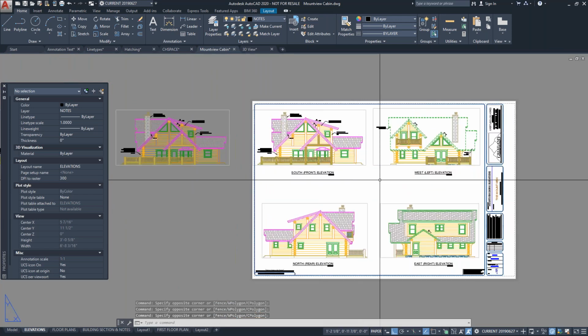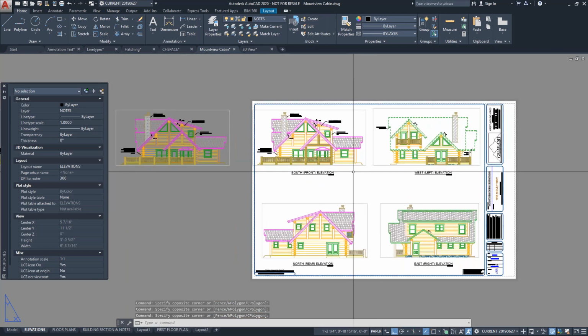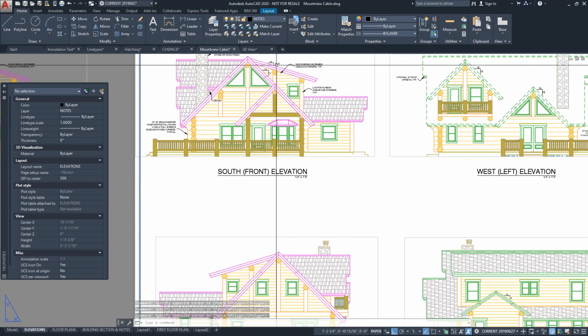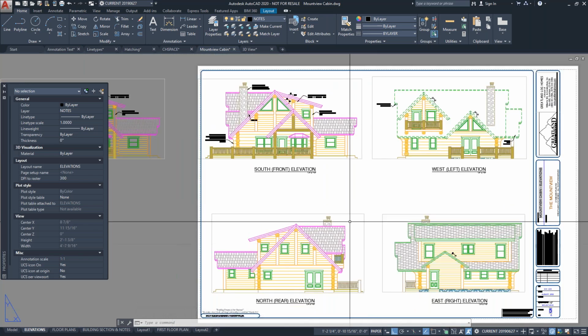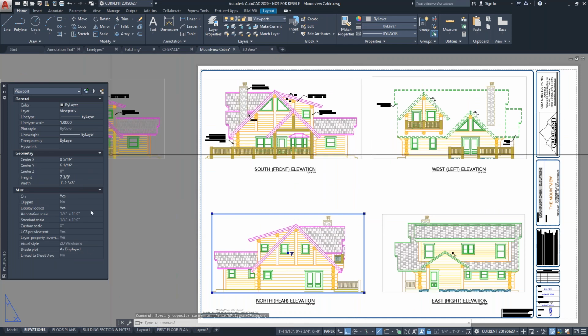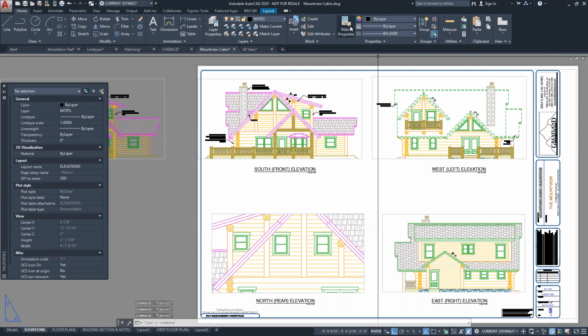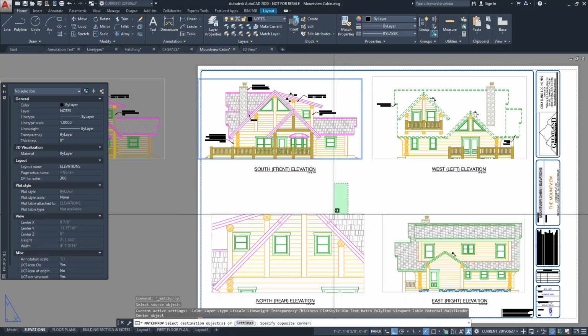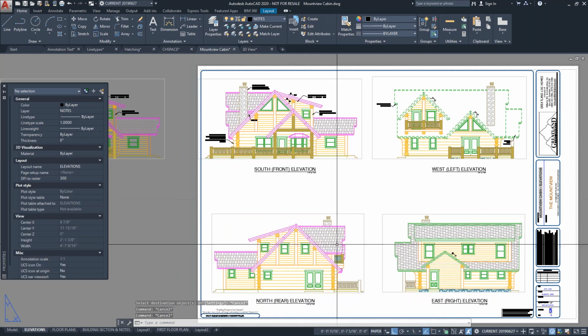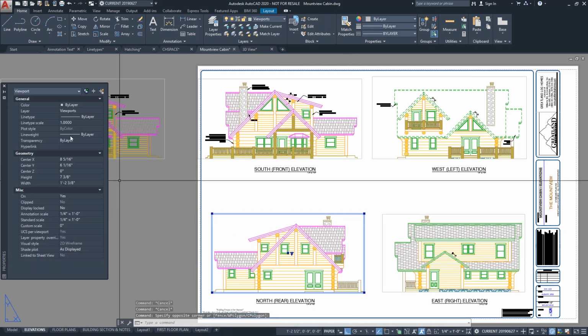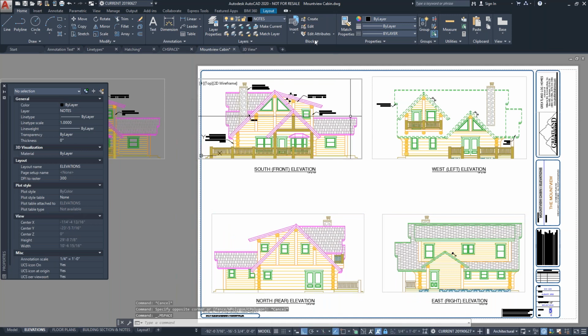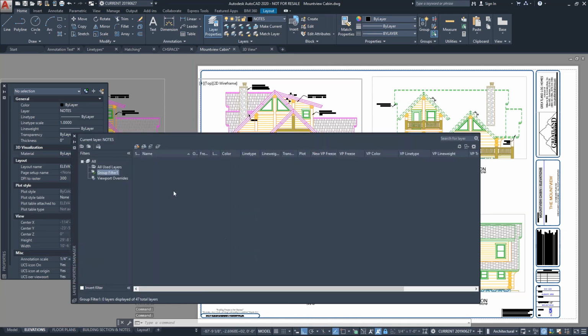Of course, it is an all or nothing environment, so you have to make sure that you want all of the changes for that viewport to be set. That would probably include the scale factor of the view. So let me verify that as well. If I change the scale factor of the view to something different and match properties, it will match the scale factor of the content as well. So anything that you see in this properties window will be modified via match properties, as well as apparently all of the layer property information.